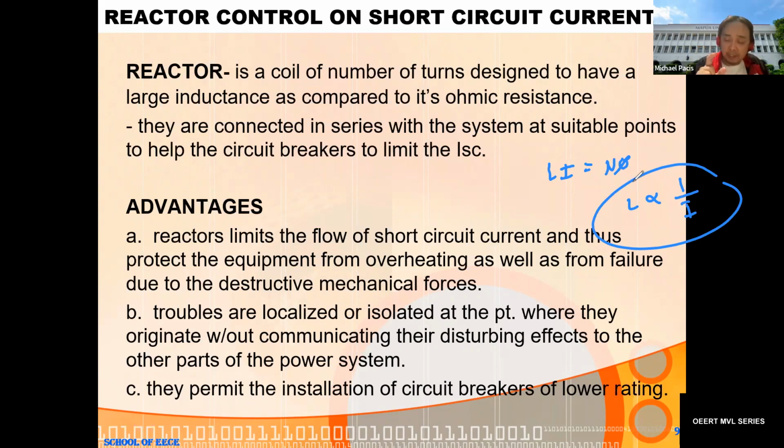So instead of replacing your circuit breaker with a new one, which is very, very expensive, you can place a reactor in series, which is sometimes practical on distribution systems para hindi po masyadong mataas o malaki yung maintenance o yung gagastusin. So it must be strategically placed in a power system.